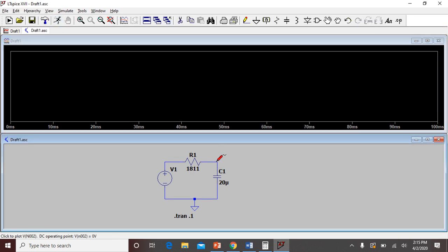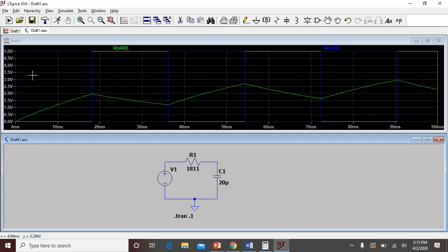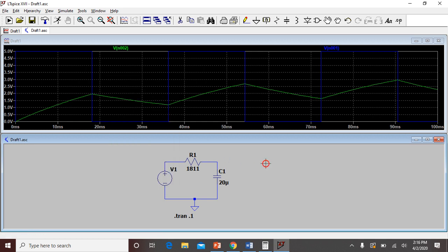And again measure the voltage across the capacitor. So now you can see the behavior is something like this, and the voltage across will be like this. We now see that once the T on time was there, since the time is on, this waveform was not fully charged, and it was charging up, but then T off started. This made the capacitor not get fully charged, and then it started discharging.